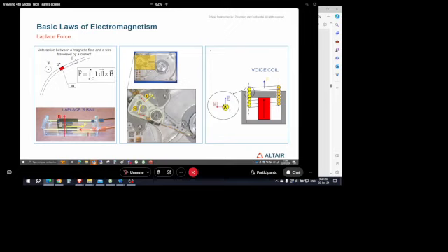But this Laplace force can appear actually on the windings, or it can appear as well on the bars where you induce the current, right? So let's talk particularly about this Laplace force on winding. If you have wires that can move inside your slot, when you supply your machine, there is a leakage magnetic flux.